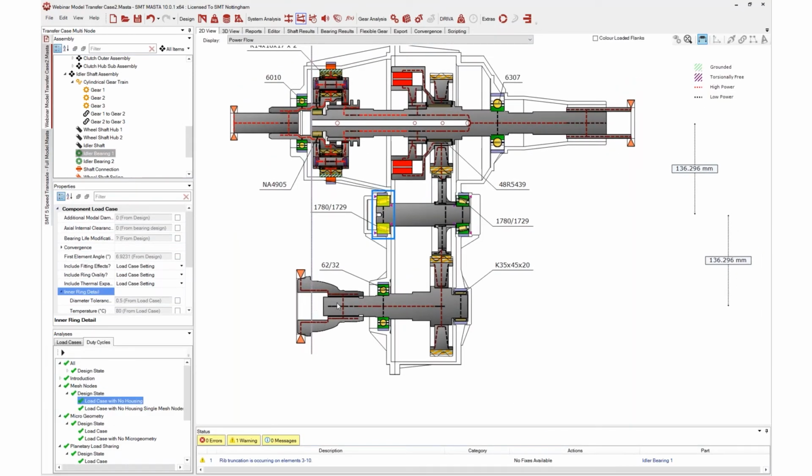As the power flows past here, we'll have some bearing losses here. And as this moves through the system, we'll go through a gear mesh and have some mesh losses. So through the system, it will keep adding up.